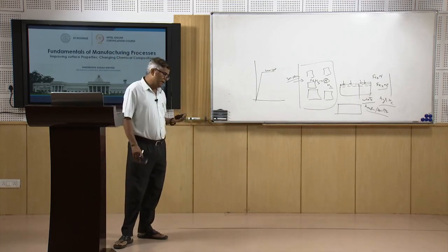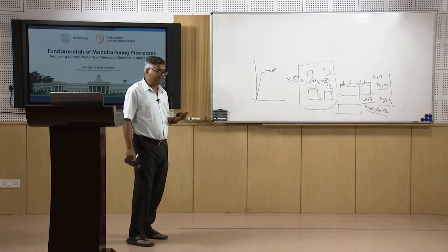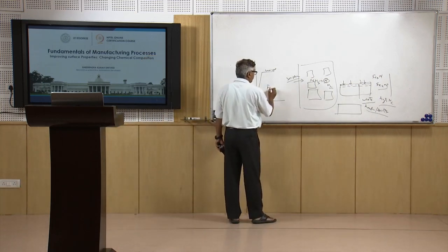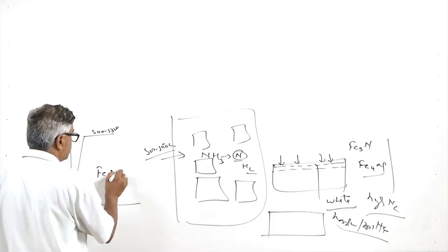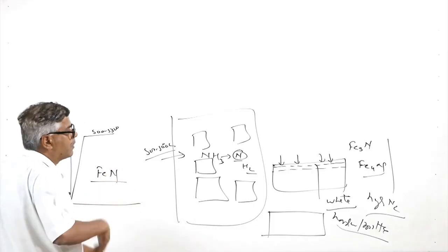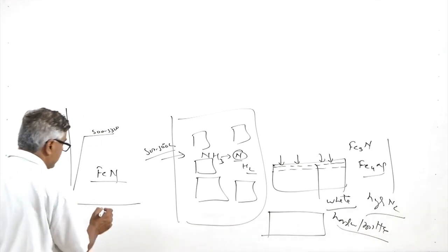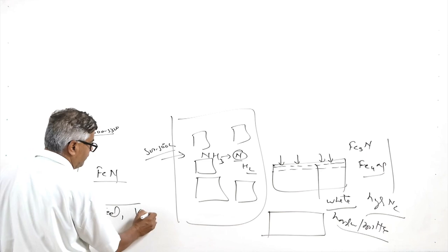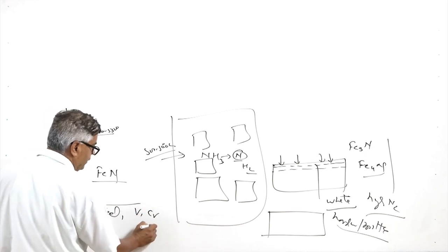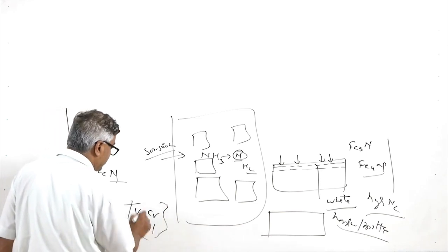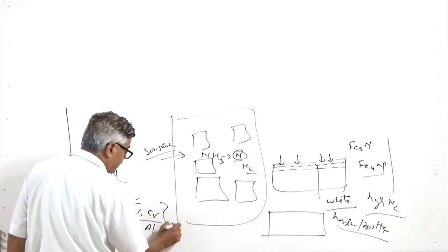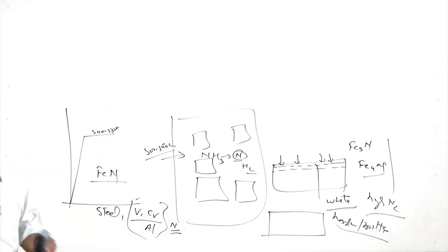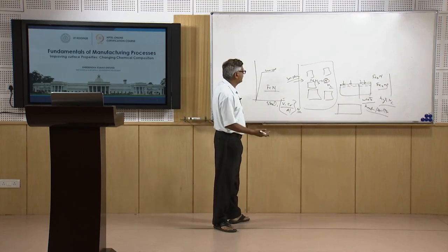Nitriding for simple steels is not that effective because it will lead to the simple formation of iron nitride only. So in order to have a more effective nitriding process, certain steels having the presence of vanadium, chromium, aluminum are used, so that they can form their nitrides effectively, and that is why certain alloy steels are found more suitable for nitriding purposes.